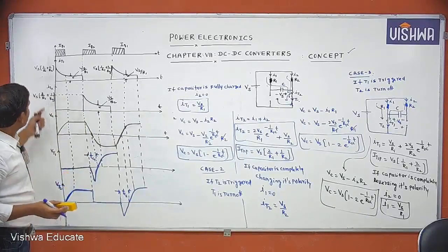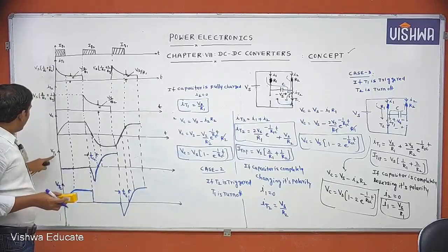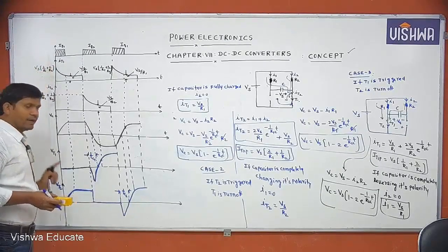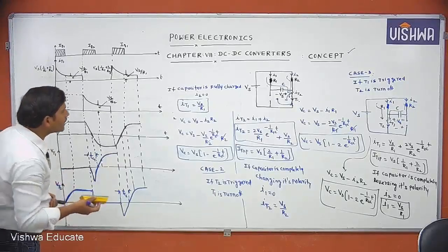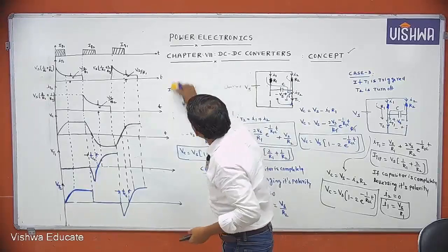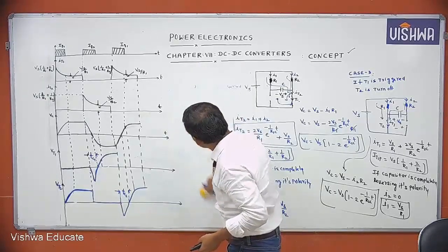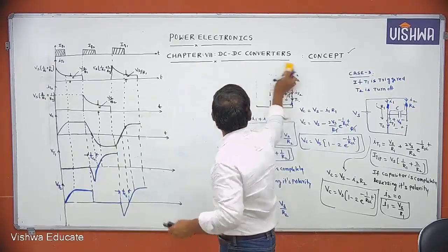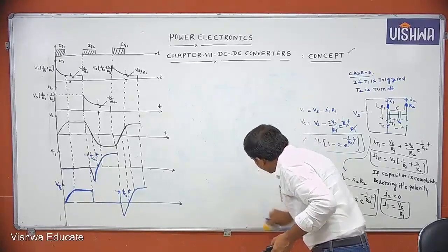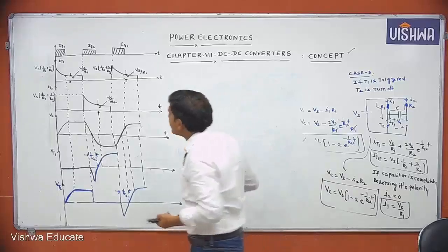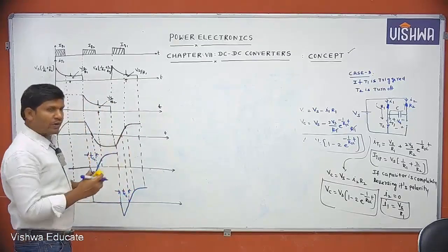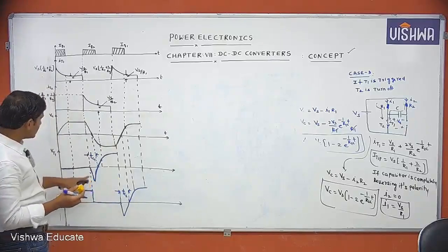Okay, this is about the voltage across VT1, VT2, the voltage across the capacitor, IT1 current and IT2 current. Clear? Okay, concentrate. Now I want to find from these waveforms the circuit turn off time of T1 and the circuit turn off time of T2. Then how to calculate them? You consider after case 2 only. Take this one from this instant.